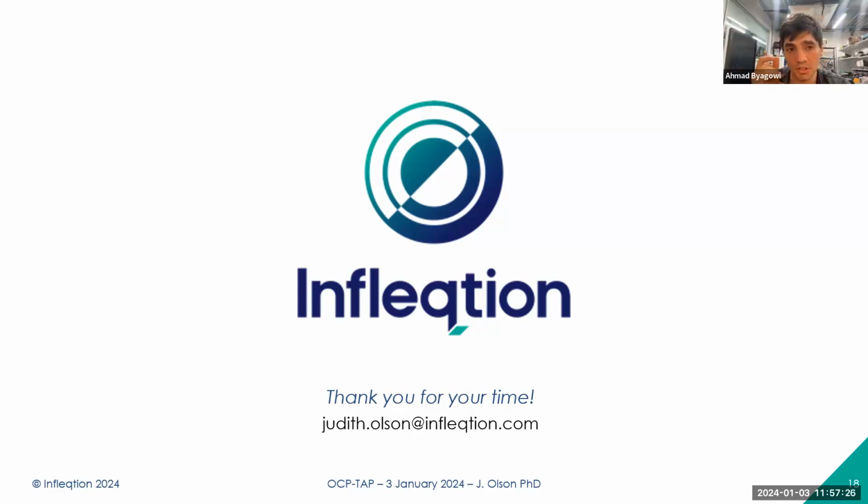So yeah, that read has also another problem again. I want to just, for reference, bring it up. Again, you get stuck with the same problem that you mentioned. Electronics cannot get you beyond, let's say, tens of gigahertz or something. Then you want to do the sampling. You have to also think about the sampling done in optics somehow, to really take advantage of this synchronization. You have, let's say, sub-picosecond synchronized two parties, and you want to send something in between. How do you want to do the sampling now in a way that you utilize this sub-picosecond precision that you have at the two ends? Electronics cannot help you with that.